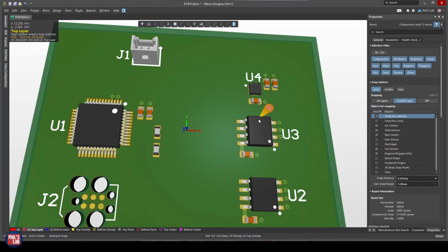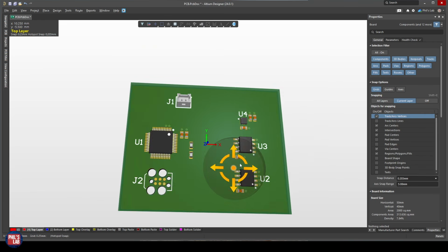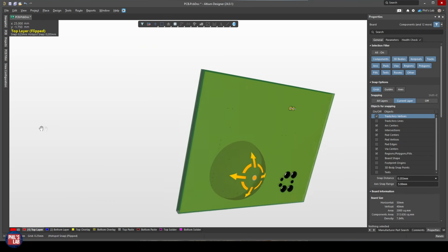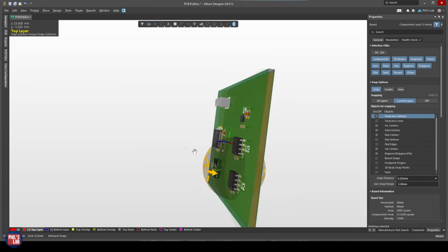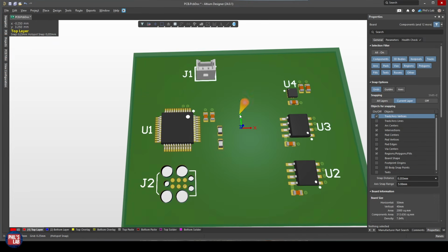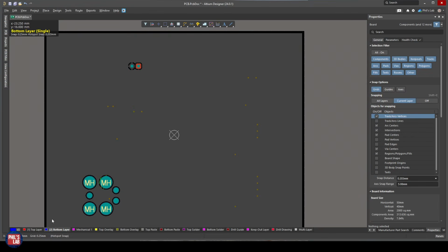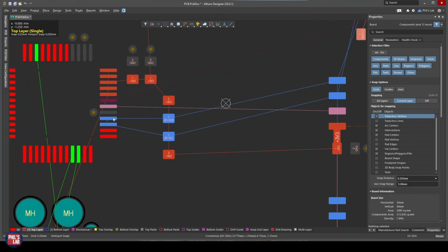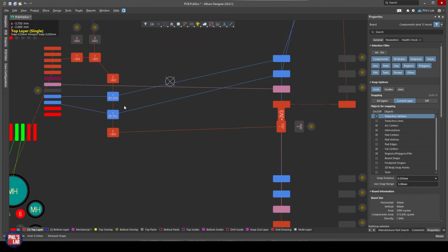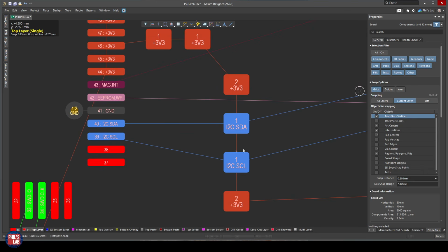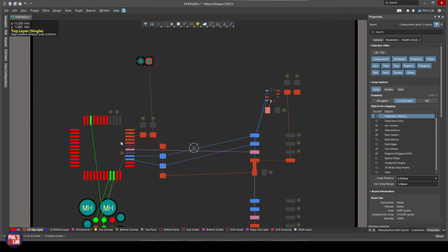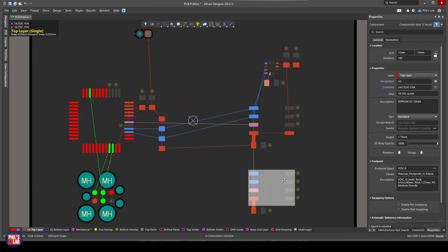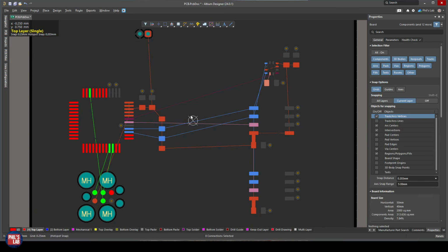Again, this is a very, very simple and rather crude example. I just want to show you how you might go about routing I2C, and actually that the routing itself doesn't matter too much. This is a two-layer board just for demonstration purposes, so the bottom layer is completely filled with a ground copper pour, and the top will do our signal routing, just as a very basic demo. If I go to 2D view, you can see the blue highlighted nets are our I2C, that is SDA and SCL, and we want to route essentially between our microcontroller and these various ICs on the right-hand side.